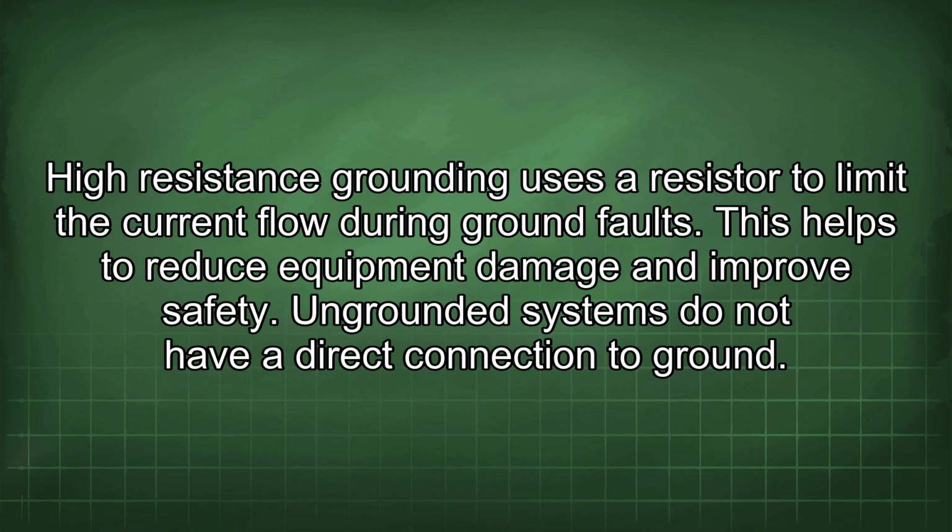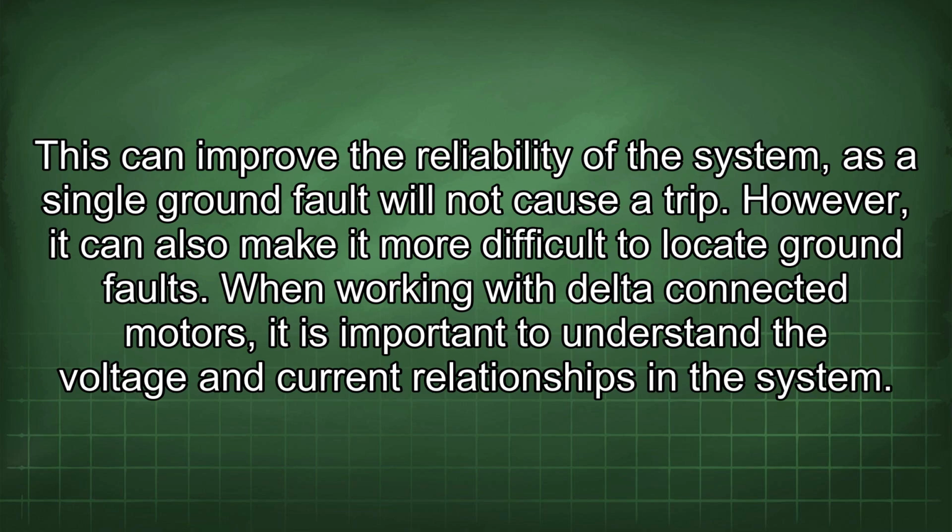Ungrounded systems do not have a direct connection to ground. This can improve the reliability of the system, as a single ground fault will not cause a trip. However, it can also make it more difficult to locate ground faults.